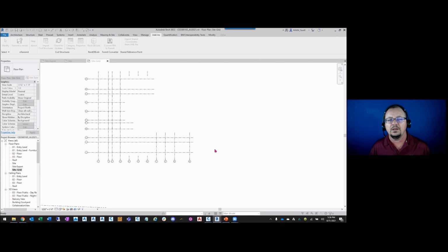I'm going to click open. Yes, I do want to create it, and okay, it successfully is created. In terms of creating the shared coordinate system, that part of the process is complete. The one thing that is often missed is actually setting that coordinate system current. So we'll cover that in the next learning objective.